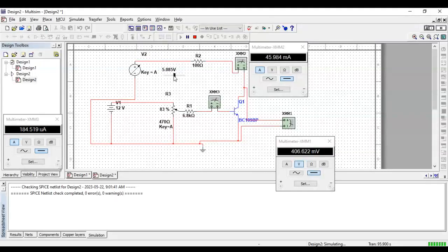And again, further at 0.6, it is 46. Small deviation, no problem. Again, 0.8 is 46, and for one more, it is also 46. So that means after increasing from 24 to 44 to 45, it has become like this. Now the transistor is working in the saturation mode.